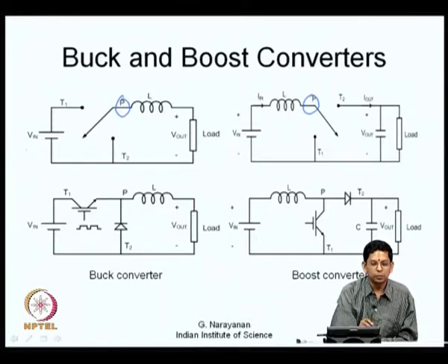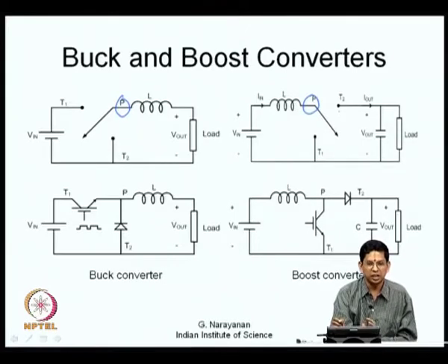Here you have the input voltage, here you have the capacitive load. So, any capacitance or a voltage source is connected across the two throws, because a capacitance should never be shorted, and an inductance or a current source should not be opened. Therefore, a current source or an inductance is always in series with the pole, but a capacitance or a voltage source should never be shorted, and therefore you have them connected between the two throws here. So, these are basic rules in connecting switches.